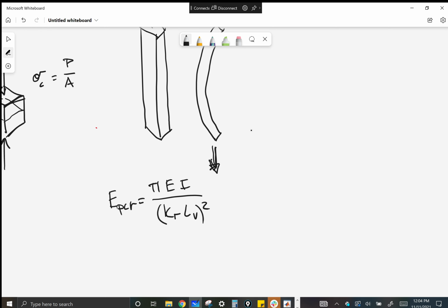And then I'll just go through it quickly, but if anybody has any questions, make sure you let me know. The most important thing is we're understanding that we're outputting a load here, not a stress, but we do have stress involved. So they're intimately related to each other, obviously. So where are we getting E from? Yeah. Material. Right. So we have to know the material for this equation to work. It's the modulus of elasticity. It's the strength of the material. It's also called the stiffness. Why stiffness? Because it's staying stiff until it starts to